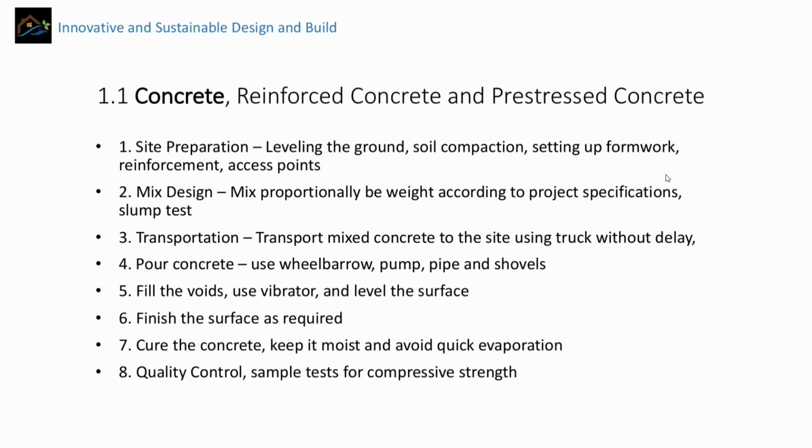After leveling the surface, we use tools to finish the surface as required. Some concrete surfaces sometimes need to be quite smooth. Sometimes, for example, if it is a driveway, then it needs to be a bit rough. It should not be slippery.